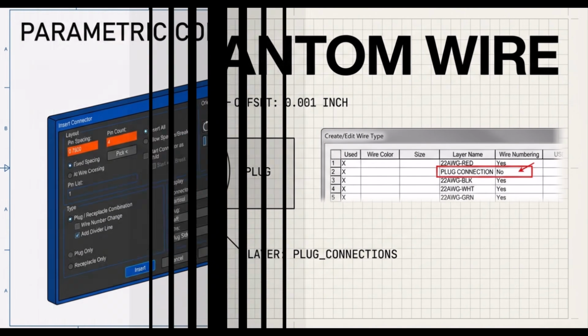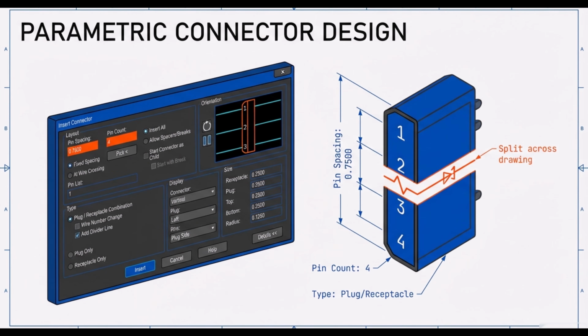Precisely. If they just touch, the database sees 2 separate objects sitting next to each other. It doesn't generate a from-to report because it assumes they're unconnected. So what's the fix? You draw a wire that is 0.0001 inches long. 1/1000th of an inch. It is completely invisible to the human eye on a printed drawing. You will never ever see it.